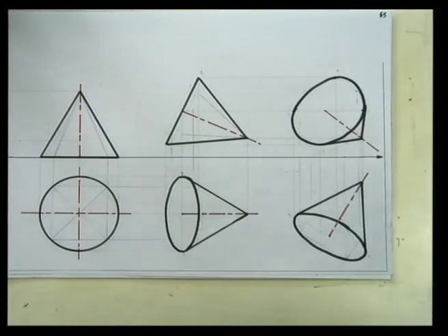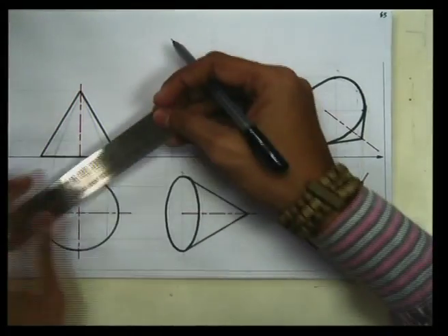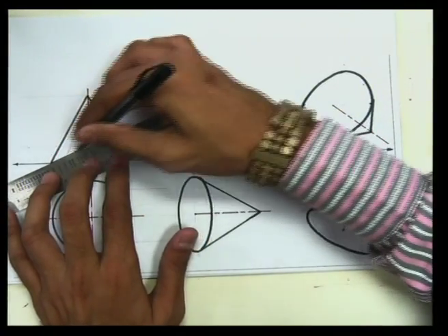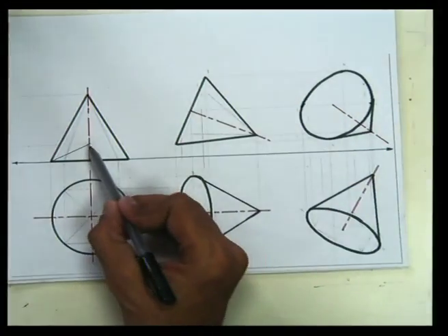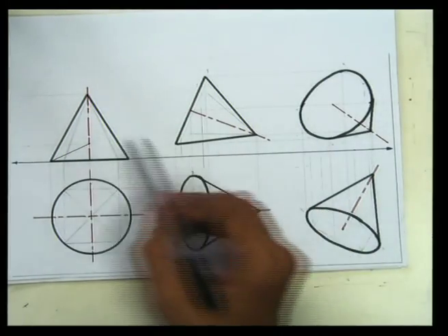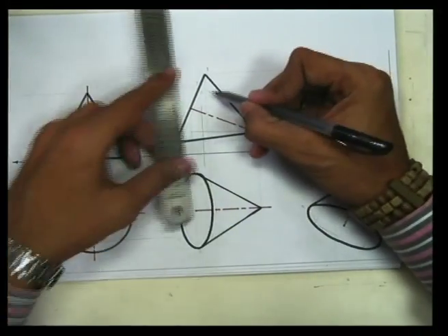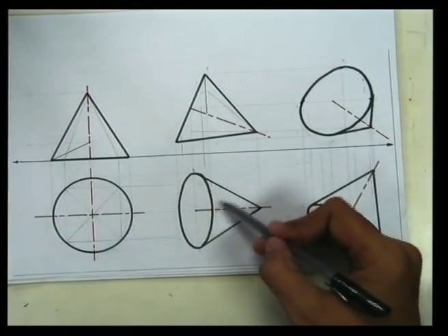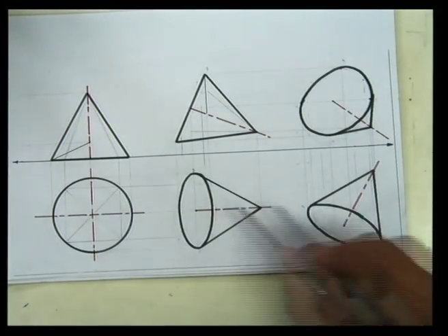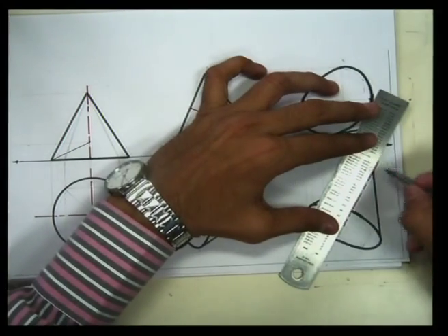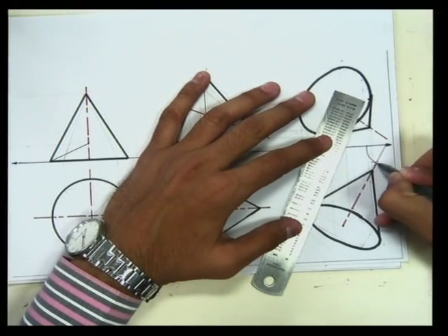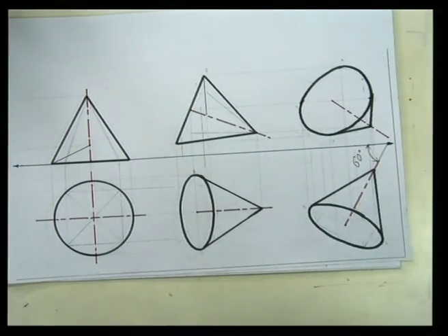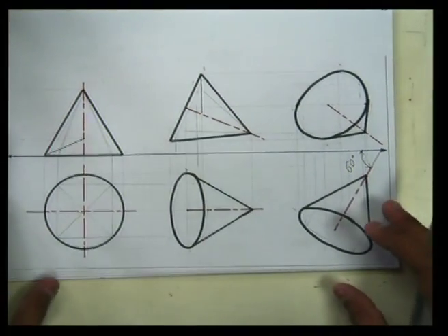In the first step, we have drawn top view and front view, assuming that it is lying on HP. Then we located its center of gravity, it is here. Then we have tilted this solid in such a way that this line AG is perpendicular to XY line. Then we have transferred the points, drawn this top view, then tilted this top view in such a way that this angle of this axis is 60 degree to XY line, and then we have transferred the points and we have drawn its front view.